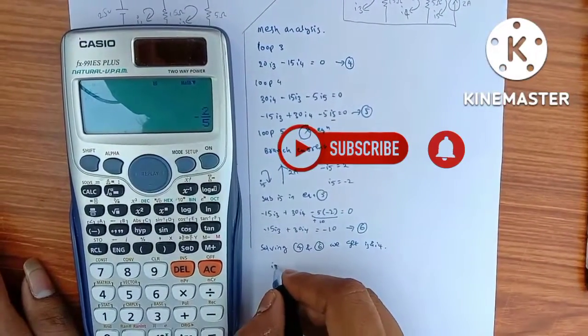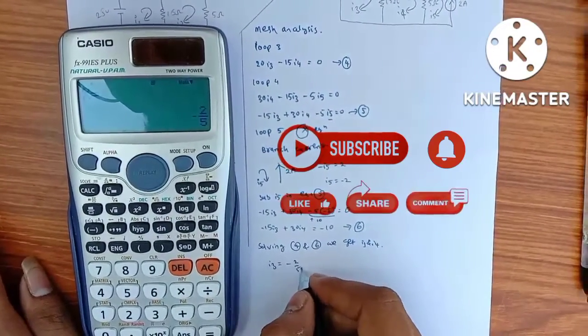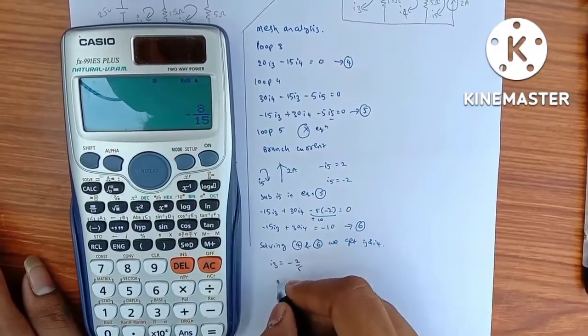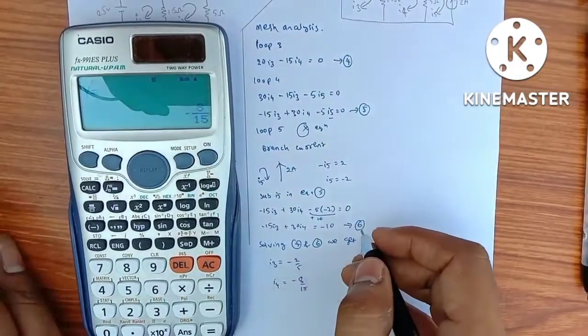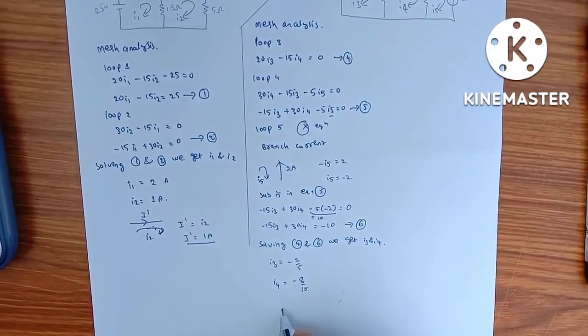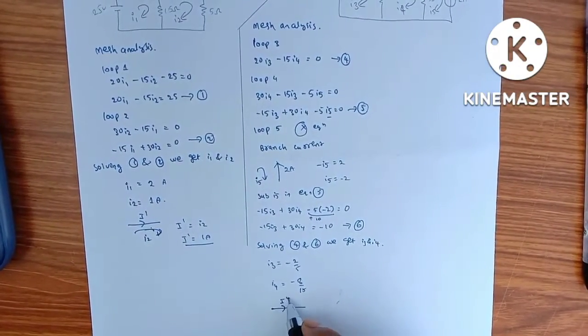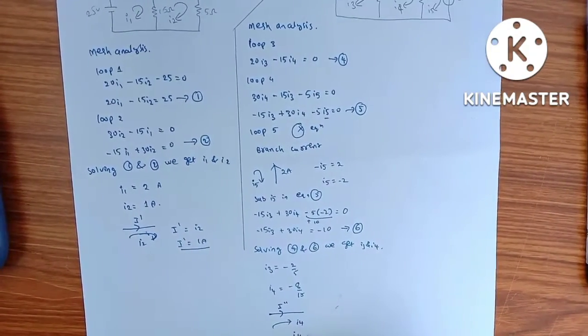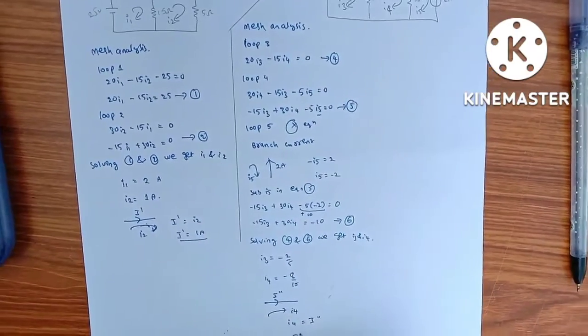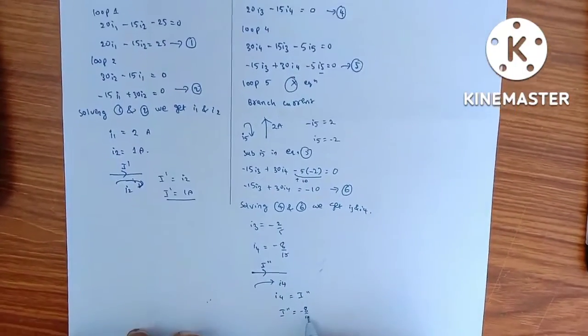Now we are getting I3 is equal to minus 2 by 5 and I4 is equal to minus 8 by 15. Now if we apply branch currents, I double dash is in this direction, and I4 is also in this direction, so I4 is equal to I double dash, which is equal to minus 8 by 15.